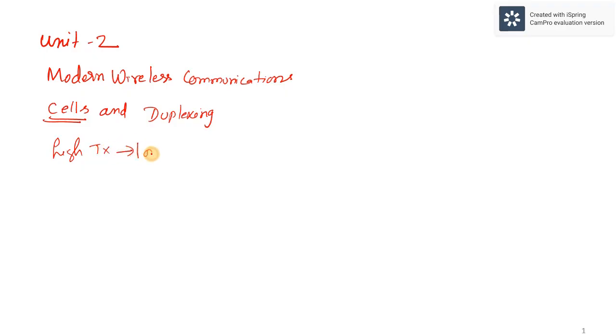Each base station is allotted a portion of the total channels, and nearby cells are allocated completely different channels. All available channels are allocated to a small number of neighboring base stations. That is the important thing in cellular systems. The interference between neighboring base stations is minimized by allocating different channels. Likewise, when it is low power, it won't interfere.